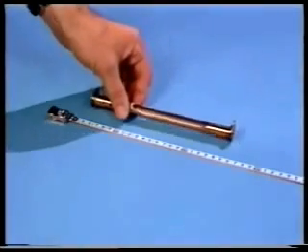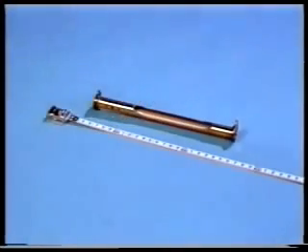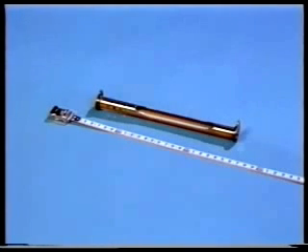Special surveying thermometers are used to take the temperature of the tape. These are laid beside the tape on the ground and left in position until steady readings are obtained. Strictly, the temperature at each end of the tape should be taken and a mean value used. If its temperature is different to the standard value, then its length will change and a temperature correction will be necessary.